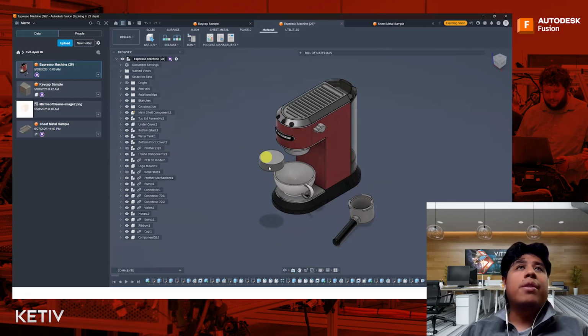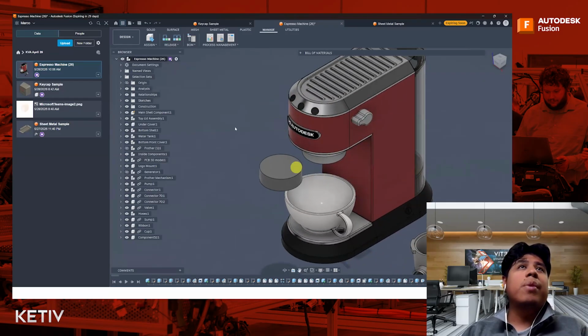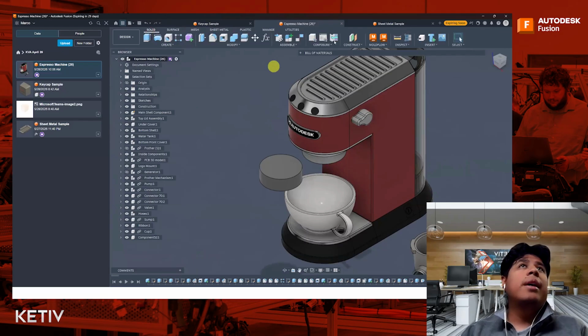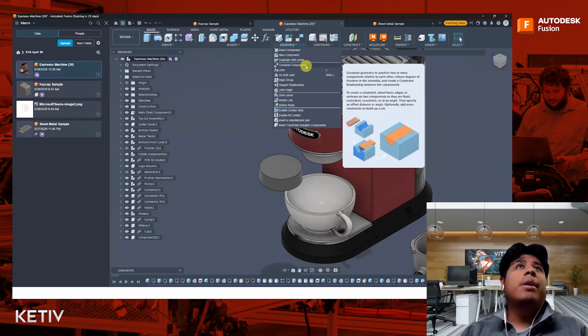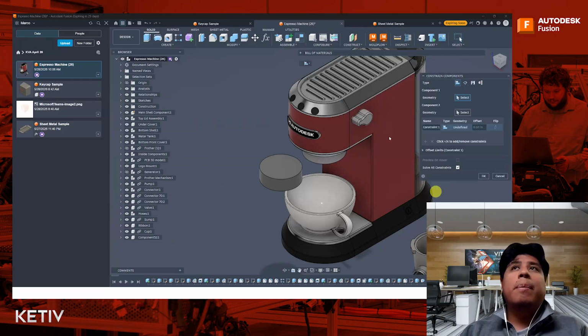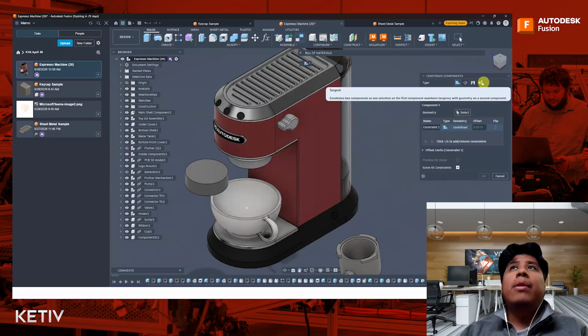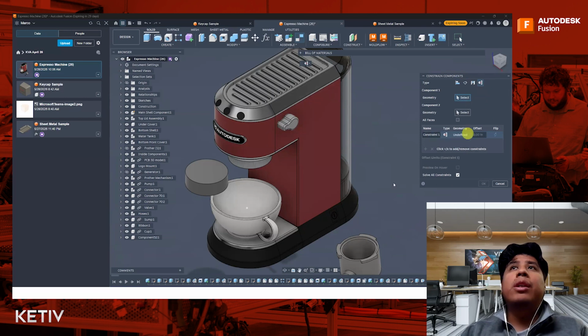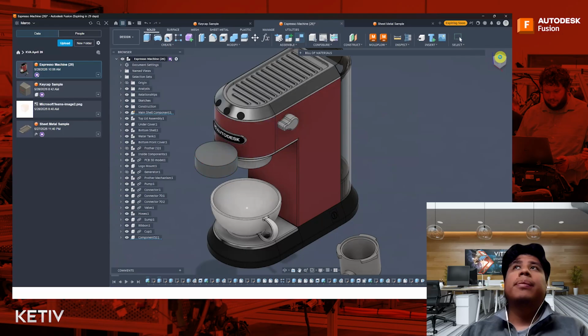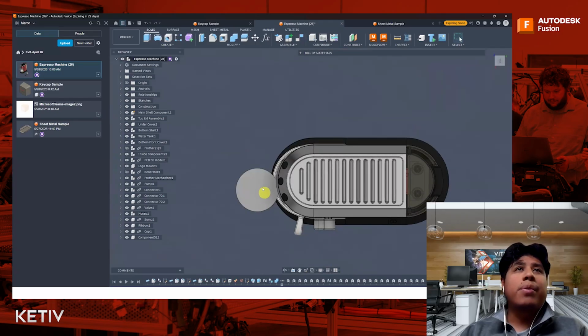Okay, so I have this little saucer here, and this is just a sample to walk through where that constraint is. Let's go to the assemble tab, and there's a constraint. And now you can see there's the last one. There's now a tangent, and this works both for edges or faces. So I can add in my tangent between those two faces, or I can select two edges and select my offset. And so now since this one isn't fully constrained, I'm going to switch this to top view. You can see that these remain tangent to each other.